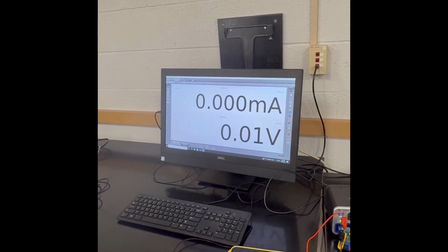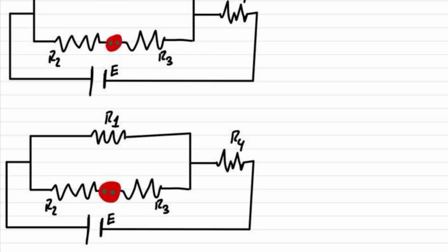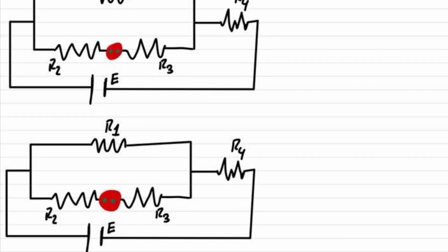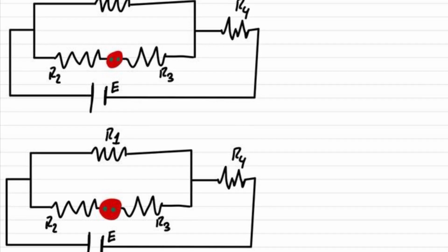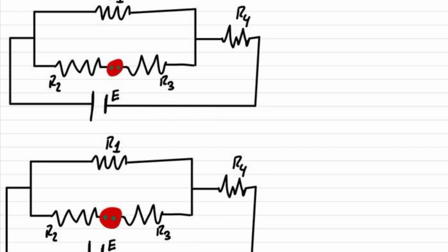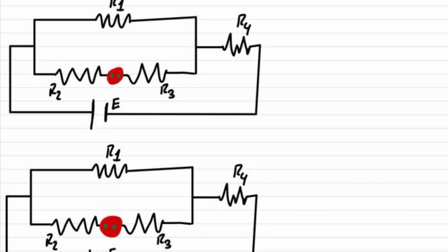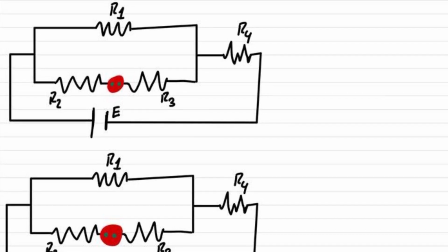I'm going to be doing the data analysis. So, as it shows with the capacitor lab notes, what we've noticed with the dielectric materials, for instance, is that the paper and the plastic material have very similar corrected capacitance along with their dielectric constants. What we've noticed and realized is the reason for that is because they're roughly the same thickness/distance in millimeters, matching at 3 millimeters. However, with cardboard, naturally, with a higher distance, there's going to be a lower dielectric constant because of that.